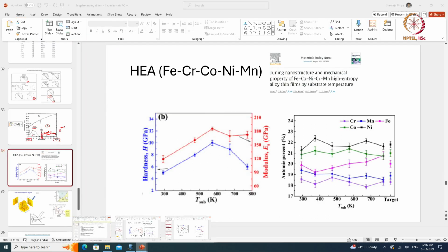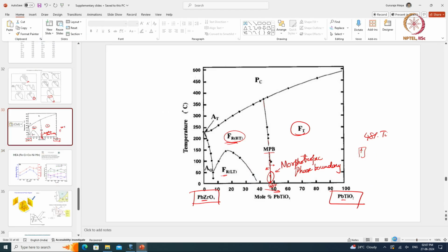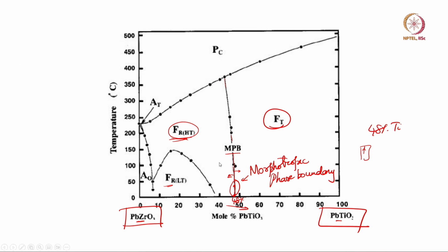It turns out, like we did in case of PZT. PZT is one of the materials that we looked at. And in PZT we made a comment in passing that near what is called the morphotropic phase boundary, the properties enhance. That's where you have a lot of options for the polarization to go to. And along the mirror plane, we said this has a Cm symmetry. So along the mirror plane, the polarization can take any orientation. As a result, if there are fluctuations, this is the configuration that will make sure that the fluctuations are all stable, and you have this energy landscape where you can have several states that jump between each other. So the fluctuations are going to be large. And so both the dielectric susceptibility and the piezoelectric coefficients are large.